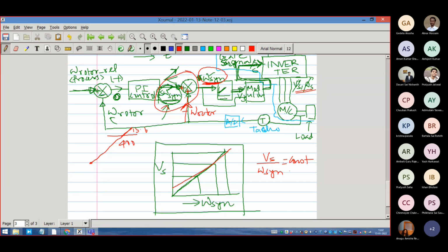It may go to 50.56 if the actual frequency is 50.56, or if it is 49.5, then let it go there. So the integrator part, I keep it to a small zone, because I already know that it is close to 50 Hz. If you don't do that, then the integrator has to work. The integrator has to integrate and reach, truly speaking, the 50.5 if it has to reach that. But it has to integrate over the entire zone. It has to feel that there is an error.